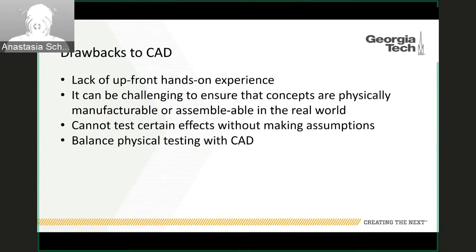And then you can't test certain effects without making some assumptions. So if you do decide to use the simulation tool in SolidWorks, it's going to be hard for you to, say, put in exact friction values for a material. So things might end up not as you would expect in the real world versus in CAD. So you do need to balance doing some physical testing versus doing it in CAD.